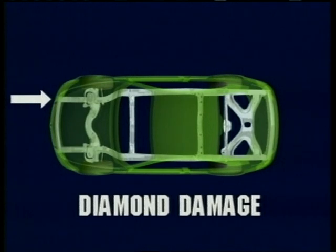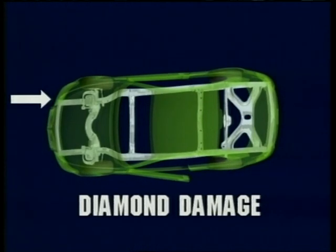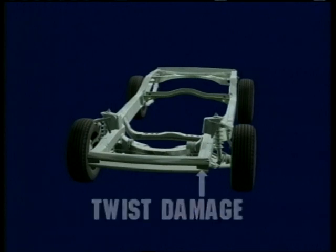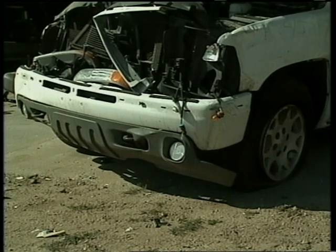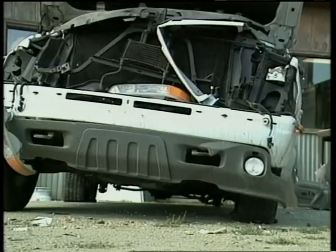Diamond damage occurs when a collision point is in line with the end of one of the side rails. The impact pushes it back, causing the frame or unibody to be pushed out of square. Twist damage is a condition in which one corner of the vehicle is higher than another. Twist can happen when the vehicle hits a curb or median at high speeds. You can recognize twist damage by a low or sagging corner, as if the suspension was broken.